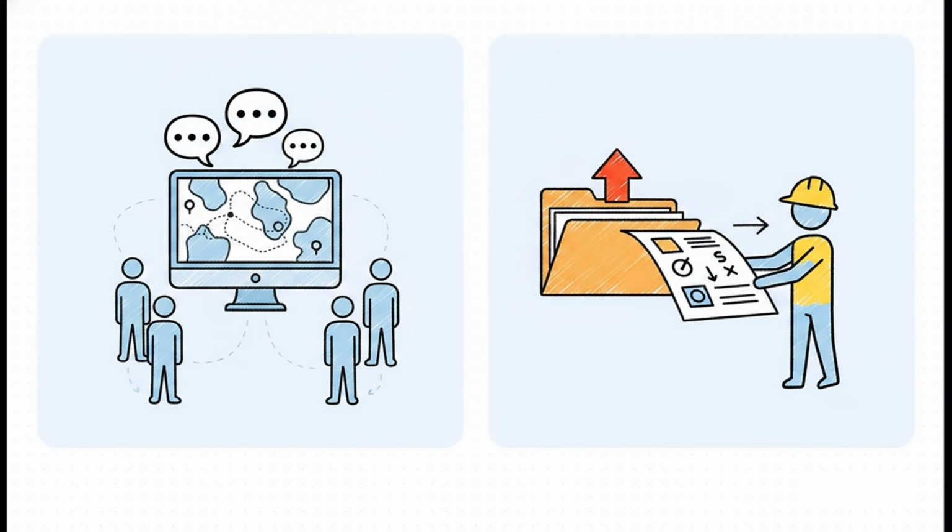Now, what's really interesting about this setup is how Nearmap handles communication layers. You have comments and you have text. If you drop a comment saying, "this crane doesn't work," that stays entirely internal. It's only visible to your project team members logged into Nearmap. However, if you use the text tool to write, "Do we need a crane here?" that text will visibly export onto the images and PDFs you send to your external subcontractors. It's a brilliant way to manage internal notes versus external instructions.